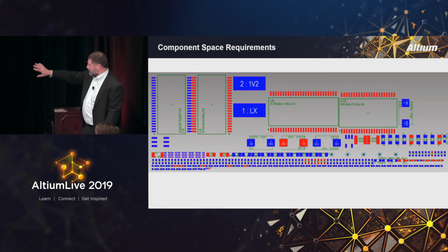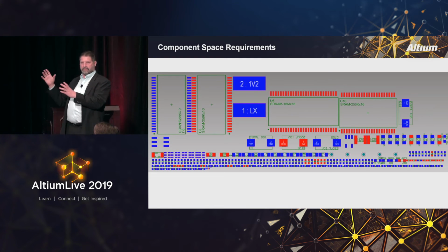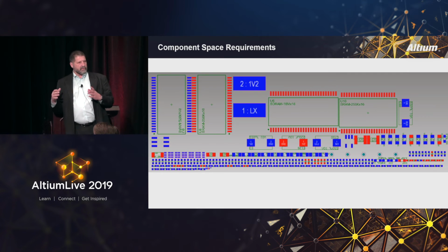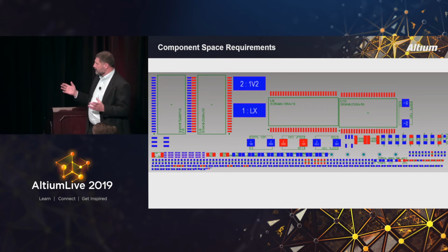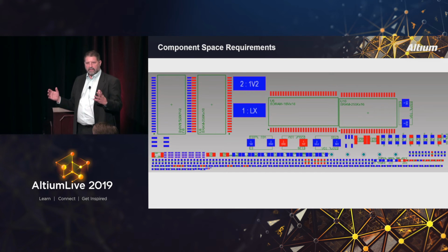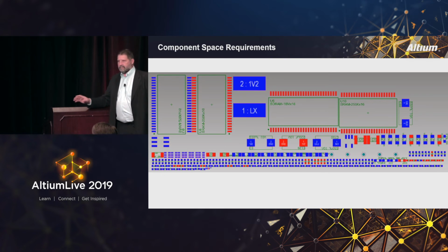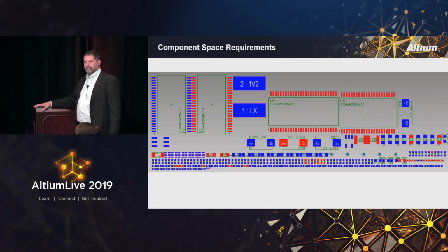So this is all the parts loaded, and we've basically just put them in, and we can measure how big this is, and we can look at that compared to our overall board real estate. If the board real estate is smaller than the component real estate, we have a problem. If it's 90%, we still have a problem. If it's in the 70 to 80%, we generally can design that. I've done designs that are component to component on the whole board, but very painful design, and it's a lot of work.